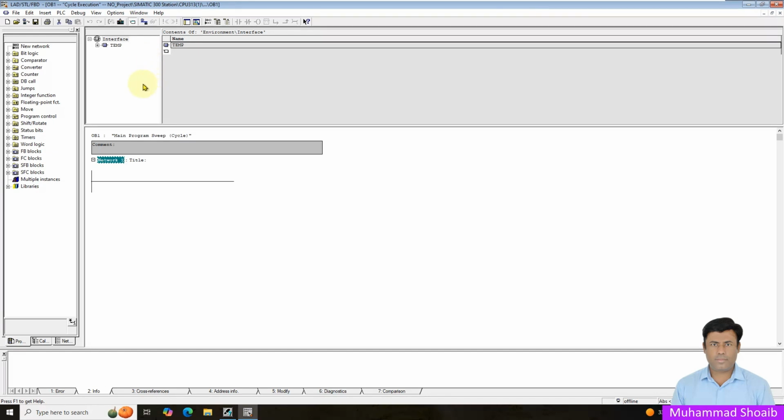So our OB1 block is open now. We'll select the network and then click here on the normally open contact.